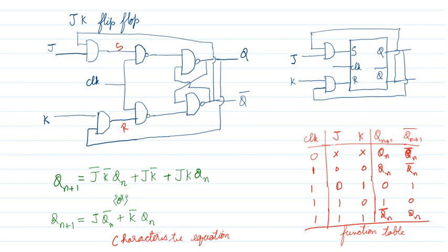If you observe this, everything in the bracket that I have mentioned here is all similar to the SR flip-flop. Only the last line is different from the SR flip-flop. When the input is 1 and 1, the next state Qn plus 1 is equal to the past state complement, Qn bar. Similarly, Qn plus 1 bar is equal to Qn.